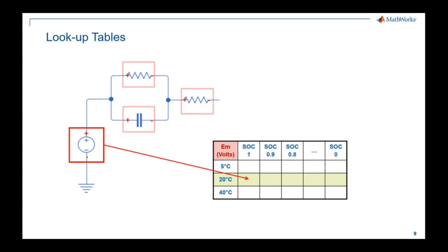Here you can see that we have 11 different values for the state of charge going from 0 to 1, and we have discretized them by splitting them by 0.1. You can be even more accurate if you add some intermediate state of charge values, like splitting every 0.05, for example. But in our case, we are accurate enough if we split only by a factor of 0.1 between each value. And the advantage here is that the thermal behavior will be represented as well. That will take into account the losses within the resistors of the battery, and also the battery electrolytes that have some thermal behavior.